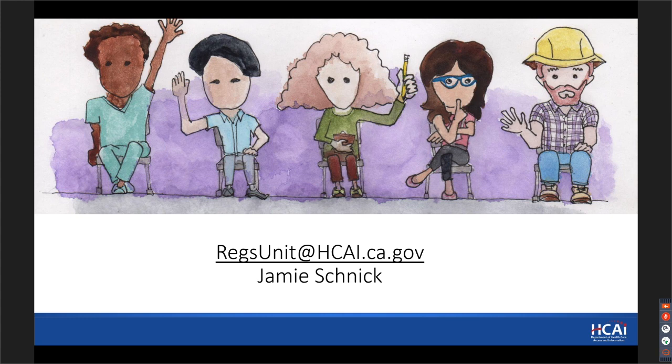Thank you, Jamie. I'll say this, let me keep it going. Foreign systems: the area above the dedicated space required to be kept clear shall be permitted to contain foreign systems, provided protection is installed to avoid damage to the electrical equipment from condensation, leaks, or breaks.